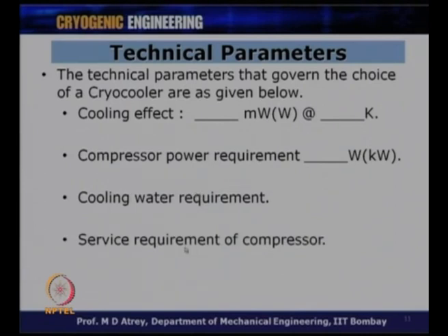Again, one has to worry about the service requirement of a compressor, because this compressor could be an oil filled compressor. The moment they are oil filled, the oil needs to be changed over a period of time, or even the adsorbers need to be cleaned or replaced over a period of time, and this talks about service requirement.